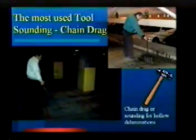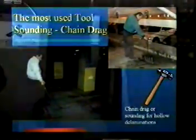There's a couple other devices. There's a hammer. I happen to like a mason's hammer. It's got a nice sharp point on the end. Sometimes you want to take out a little bit of concrete. But here also, you can tap it on the concrete and take a listen to it. There's a couple of sophisticated devices. One of our exhibitors out here has a very nice device that you can roll along the concrete to take a look for it. But we're looking for delaminated concrete. A couple other tools that you have to have. Gotta have a flashlight.